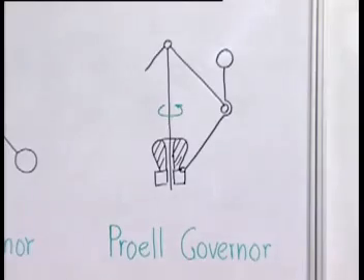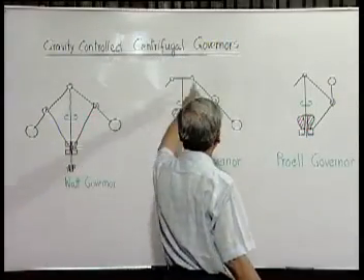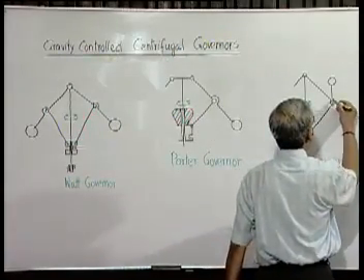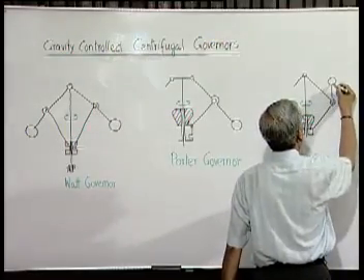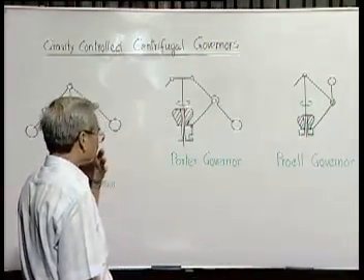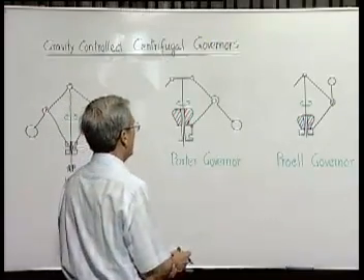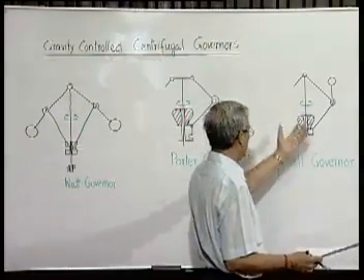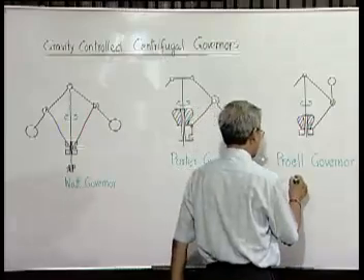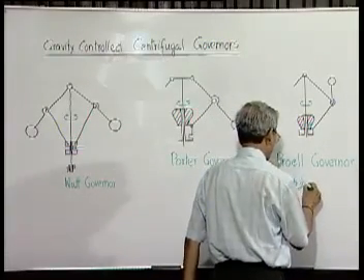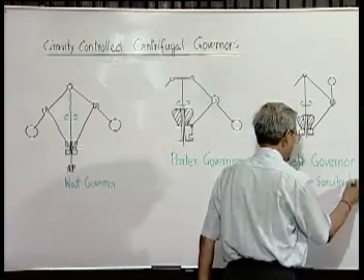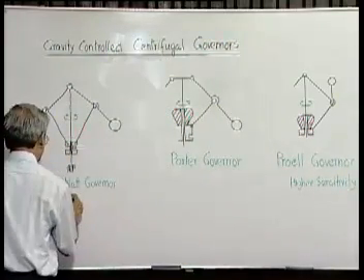Here the spherical balls are not placed on this pendulum like member, but instead it is on the lower link, which is extended beyond the hinge point here, and this sphere is mounted on this part of this extension. This improves the efficiency further, and here of course we also have a central weight to control through gravity. So, this provides much higher sensitivity. So, these are the developments through ages. This is the lower sensitivity.